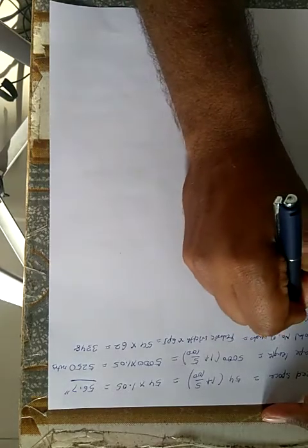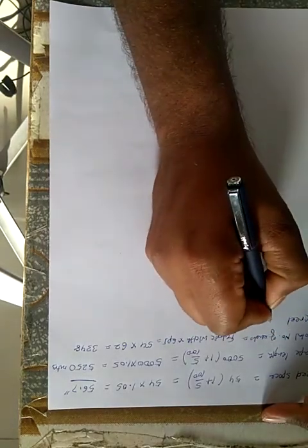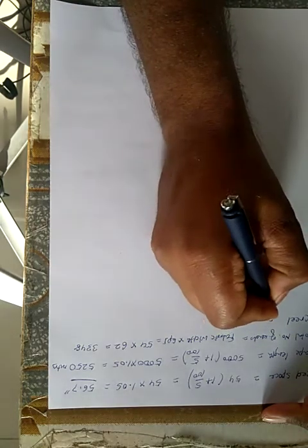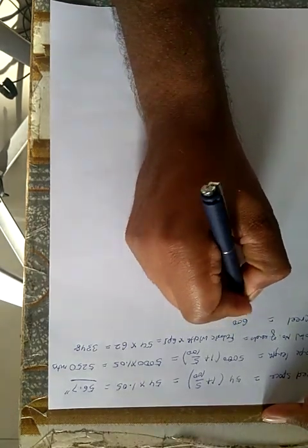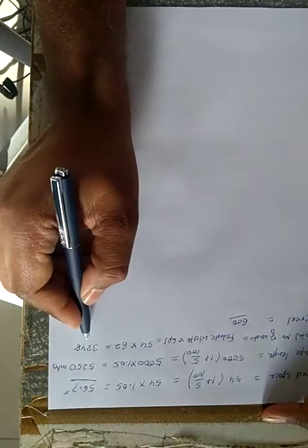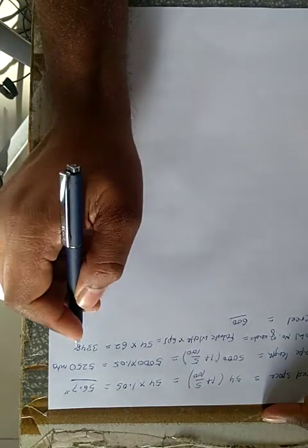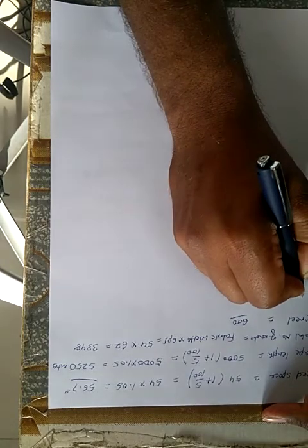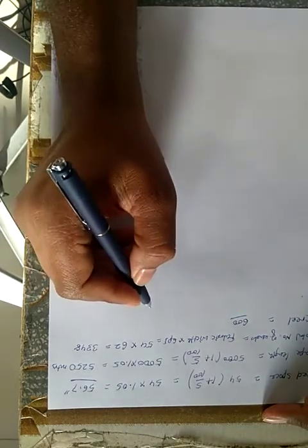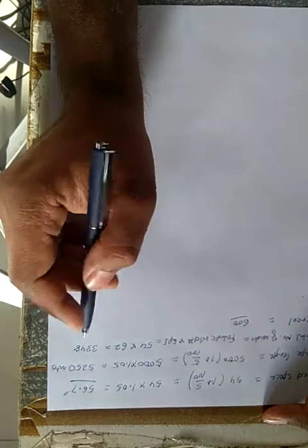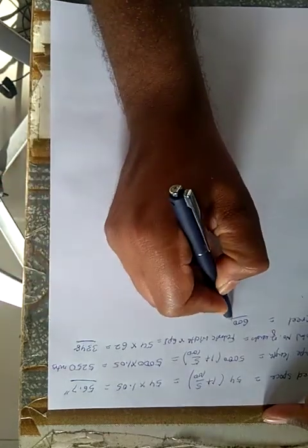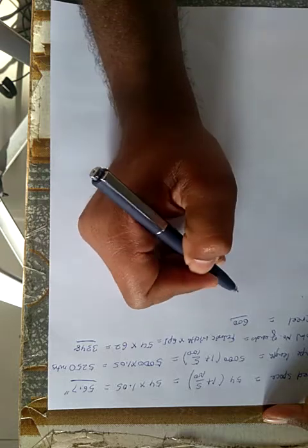Now the creel, the total capacity we have is 600 and we have total number of ends 3348. So now we will find out how many warper's beams we have to produce, because the total number of ends is much higher than the creel we have.